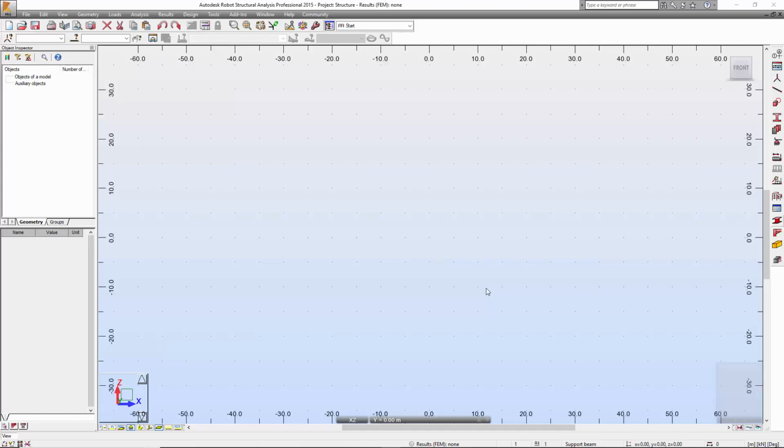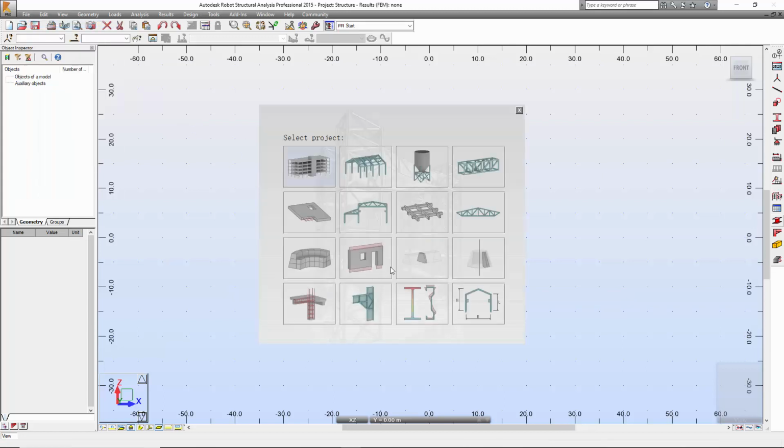Autodesk Robot. So let's load up this Autodesk Robot, and then start a new project. When we model this one, we are not using the truss structures because we're going to put a column, and then we're going to put a beam in, and also because the beam support is going to be perpendicular to the plane, the truss structure plane.